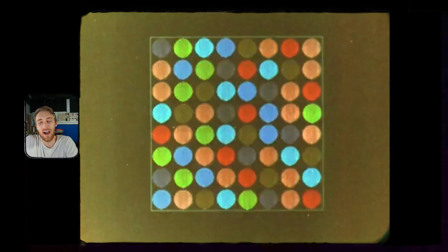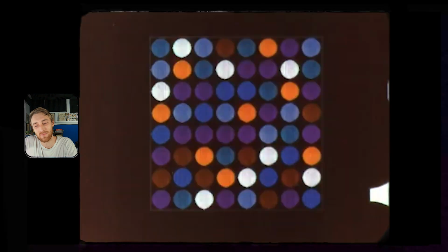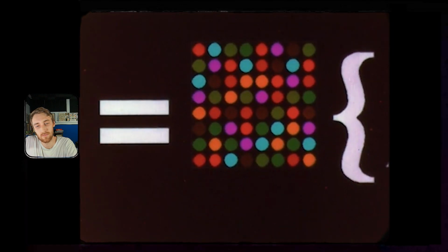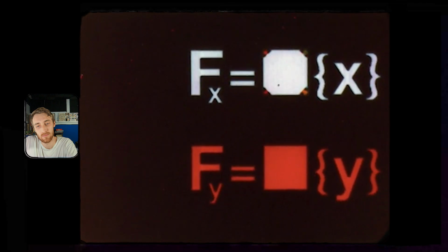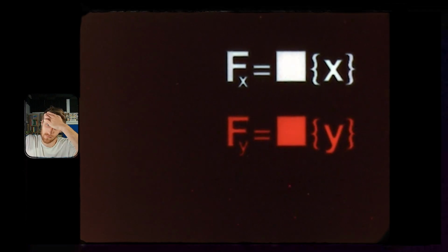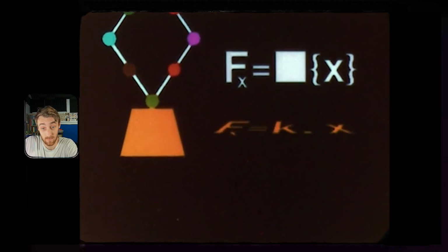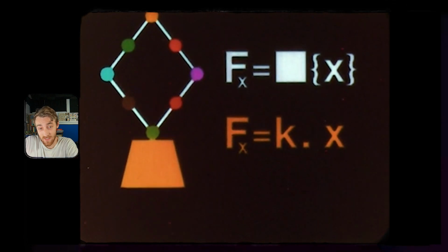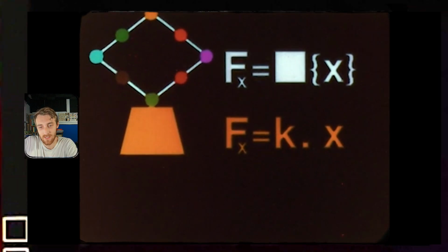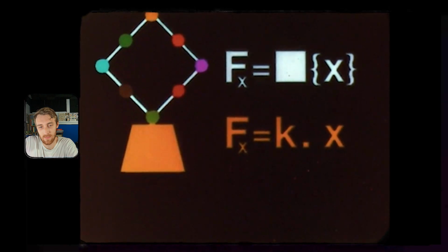And from this, we derive potential energy. And finally, from minimum potential energy, we obtain a pair of system equations for the complete element. By analogy with the equation of a simple spring, this new matrix is called the stiffness matrix for the element.